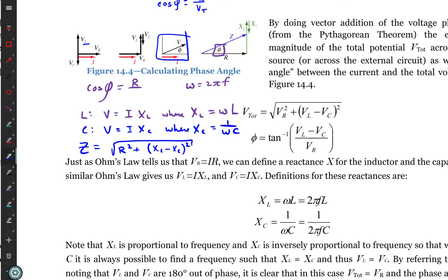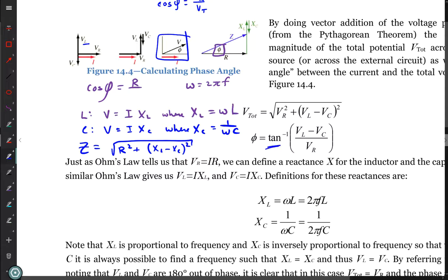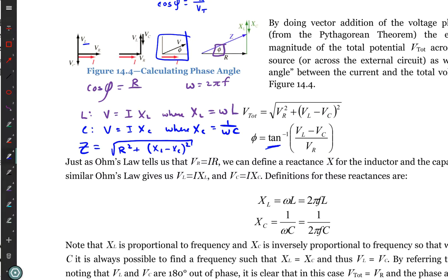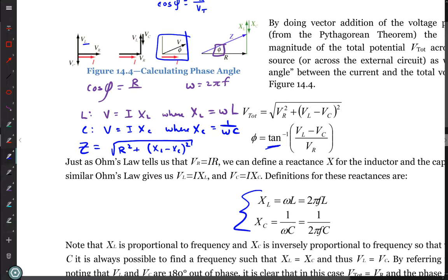So hey, look, these equations look very similar. What's the difference in what I did? I did it in impedance. In my lab guide, which I also wrote, I did it in voltage. But you can see that these are the same. Oh, I used tangent here. Tangent is just going to be opposite over adjacent instead of using the hypotenuse. So it's the same idea. And here's those equations for the two impedances.